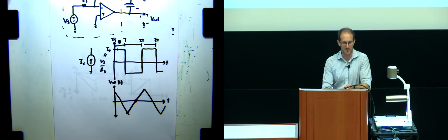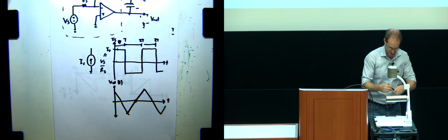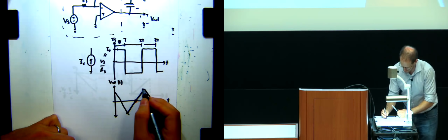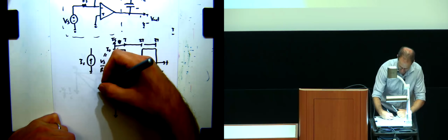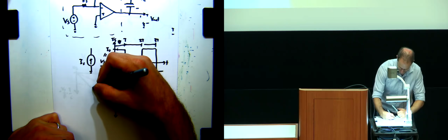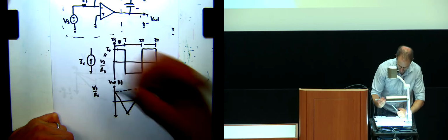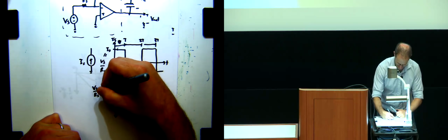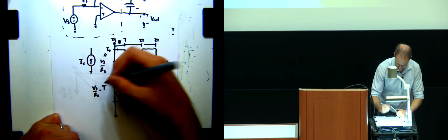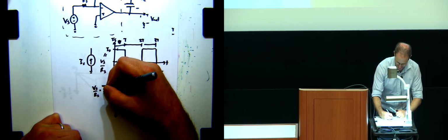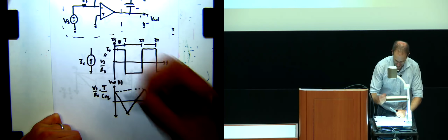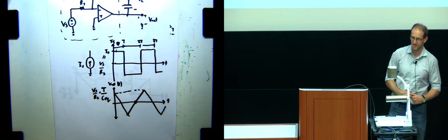What does the touch do? What does it change in this whole picture? It changes the capacitance, right? Okay, and maybe I'll explicitly write it out. This value over here, as a reminder, is just Vs over Rs, which is the current, times the amount of time that you basically allowed this to run, divided by the value of the capacitance, right?